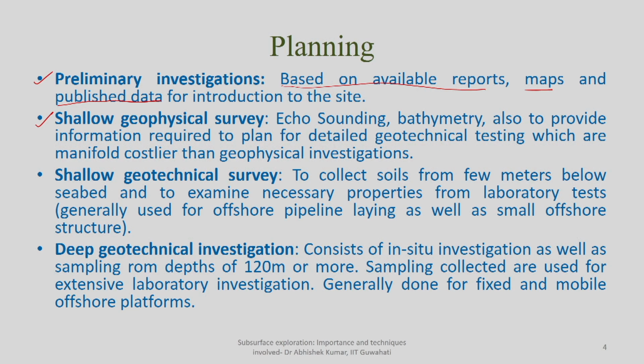Then, after preliminary investigation, you go for shallow geophysical methods, which precisely consist of echo sounding, as we discussed, and bathymetry for water depth determination as well as for mapping of the sea floor and possible obstacles on it. This will also indicate how suitable it is to go for detailed geotechnical investigation.